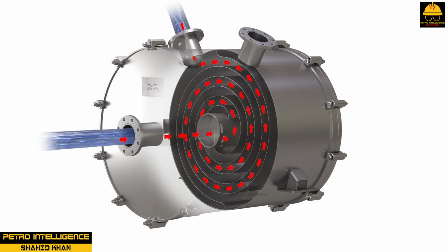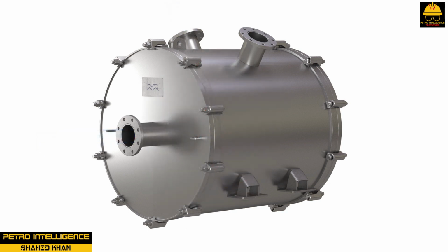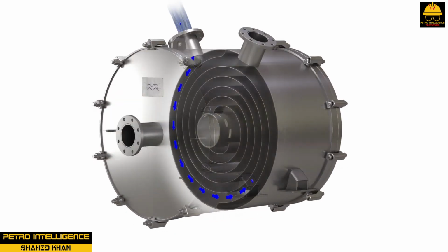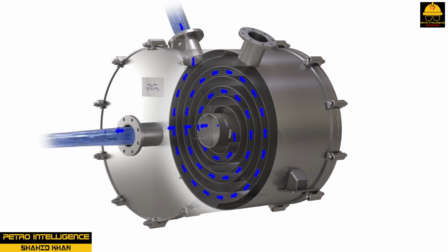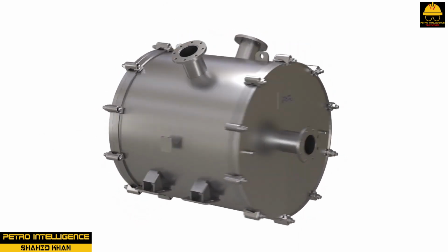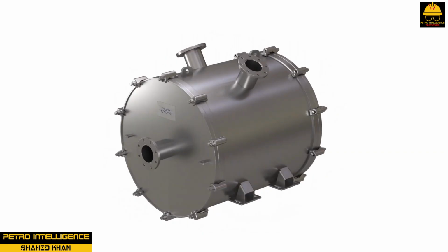Type 2 spiral heat exchangers are designed for use as condensers, gas coolers, heaters, and reboilers. The vertical installation makes it an excellent choice for combining high liquid velocity and low pressure drop on the vapor mixture side. Type 2 spirals can be used in liquid-liquid systems where high flow rates on one side are offset by low flow rates on the other.